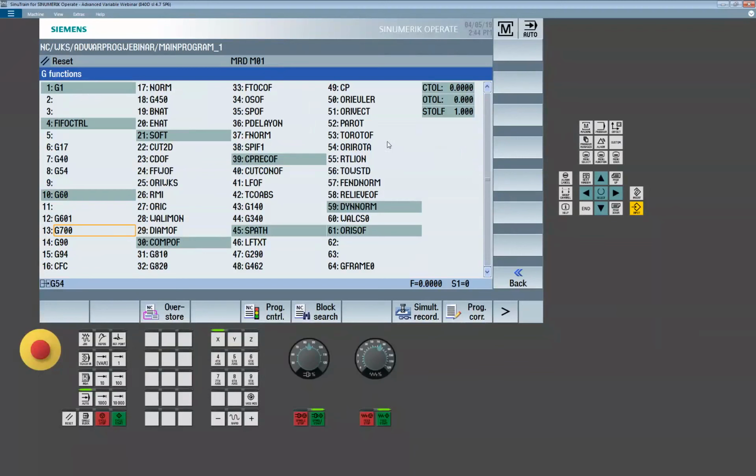That's the G-code group. So in my case, I come down and I say, okay, well, where is G70, 71, 700, 710? Where does that exist? G-code group 13. So if I query or check the state of G-code group 13, it's going to pass me back a number, a value. Now, if you don't know what these values are, you can dig through our documentation and we list them all, or you can just kind of test it, right? So that would be an easy way to check the state of that G-code group.